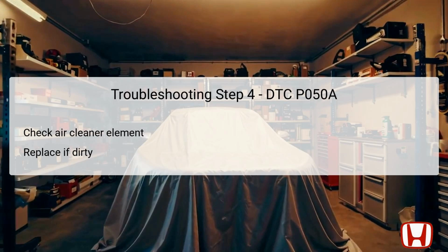A dirty air cleaner element can lead to inadequate airflow, resulting in poor engine performance and potentially triggering DTC P050A. If found soiled, replacement of the air cleaner element is necessary to restore proper airflow and filtration. After this step, ensure that the new element is properly installed. If the element appears clean, you can then proceed to verify potential problems in the subsequent steps, maintaining a systematic